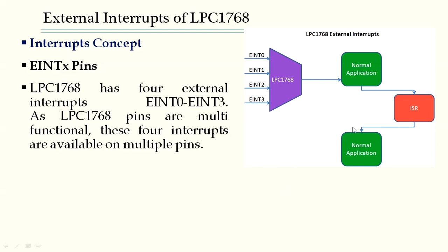So, you could find there is some amount of similarity between call to a function and the interrupt. But the major difference, what I said was, if it is a function, you're sure that after 5 instructions, I have a call to a function, or after 10 instructions, I have a call to a function, and the control is transferred, executed, and comes back.